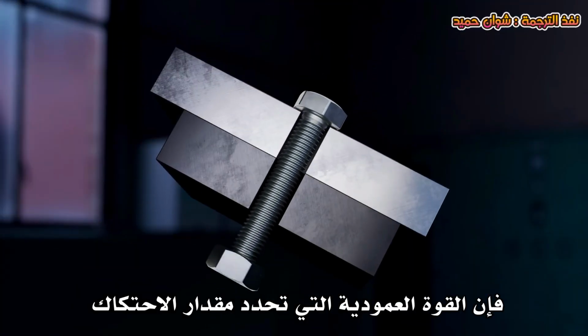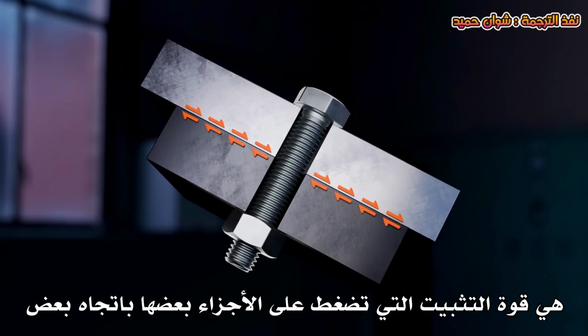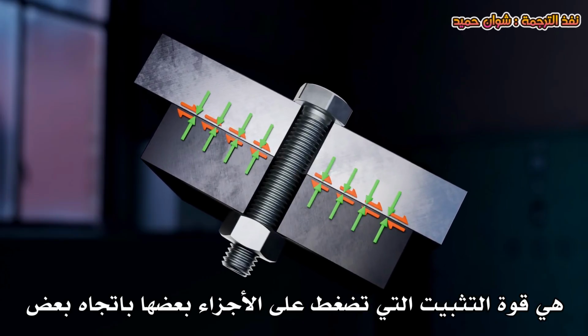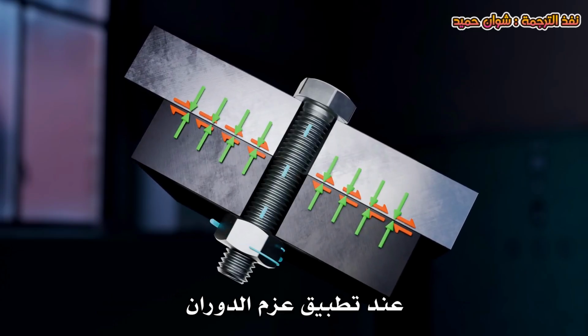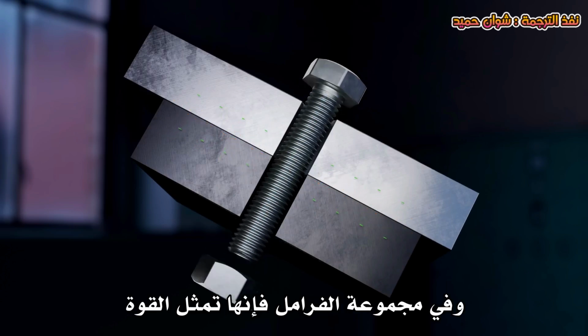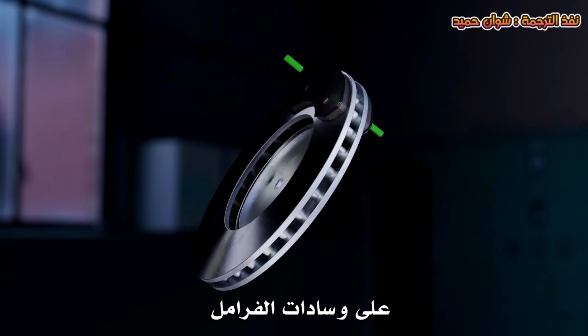In a bolted joint, the normal force that determines how much friction there is between the two joined parts is the clamping force pressing the parts against each other. It's equal to the preload generated in the bolt by applying torque. And in a brake assembly, it's the force delivered to the brake pads by the mechanical or hydraulic system.